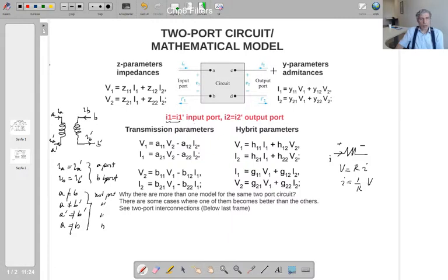And there are two ports. You can use one port as an input, the other port as an output. So our aim is, what is the input-output relation of those two ports? Since it is just one port, two representations. In here it is two ports. The input-output relations can be written in 6 different ways. That is one of them. We are saying input-output relation. So at the input port of this element, we've got two variables, V1 and I1. In the other output port, we've got two electrical quantities, one of them voltage, the other current, V2, I2. So what is the relation? This V1, I1 and V2, I2 relation could be written like this.